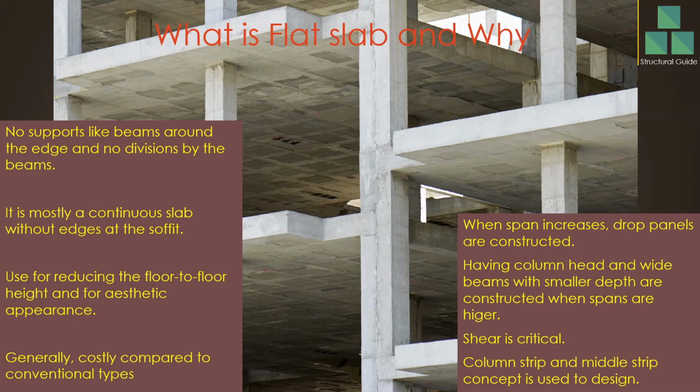Shear is critical. Not like normal conventional slabs, here the shear is critical because the slab is supported by a small area like columns or drop panels. Small area, not like conventional slabs, where we have a continuous support. Here we use small supports. In the design, we consider the column strip and middle strip concept to design these slabs.